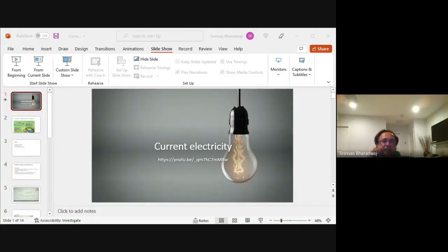Okay. See, but in some cases, instead of KVL and KCL, KVL is what? Kirchhoff's voltage law, KCL is Kirchhoff's current law. Instead of those, you first reduce this. In this case, you see these two are in parallel, just combine them. 6 and 6 equivalent is 3. 1 by 6 plus 1 by 6 equals 1 by 3. So you replace it with the 3 ohm resistor, and then you have two equations and two unknowns.